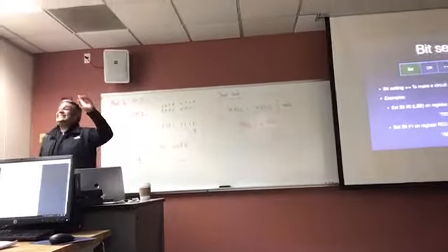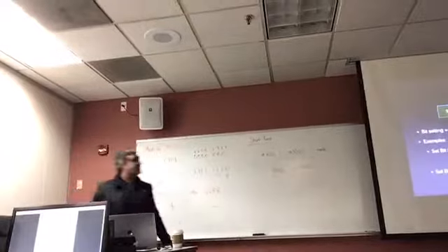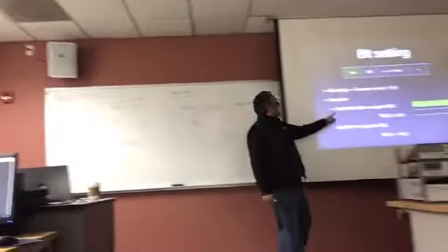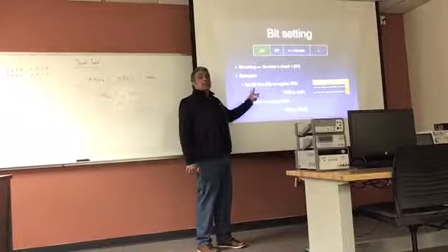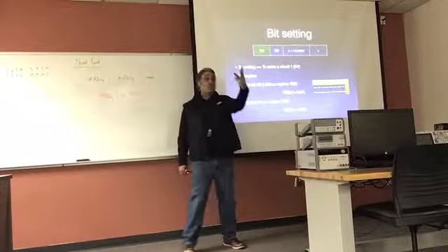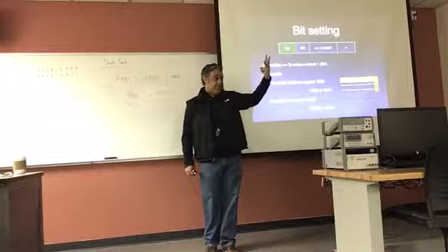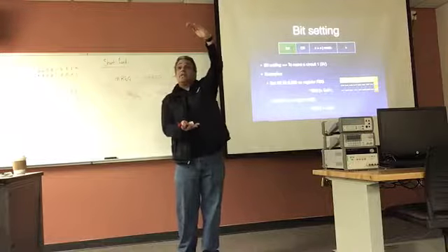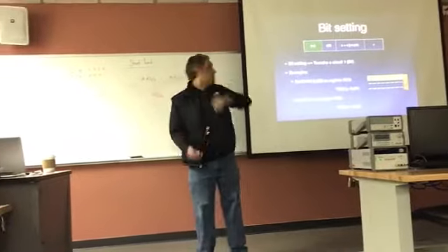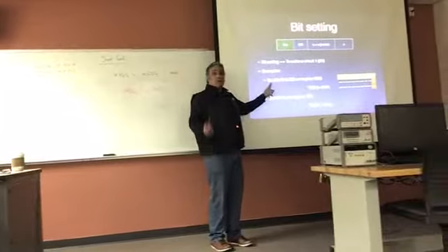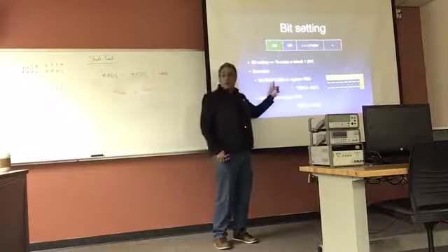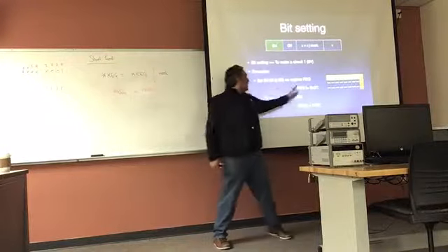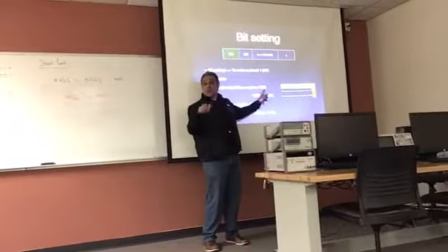So at the end of the day, every time that I hear the word set, you can pretty much close your eyes and know that there is only 3 pieces of information I need. I can write a sentence this big, and the only 3 words you're looking for are the word set, what to do, the big number, where to do it, and the register, the circuit you want to work on.